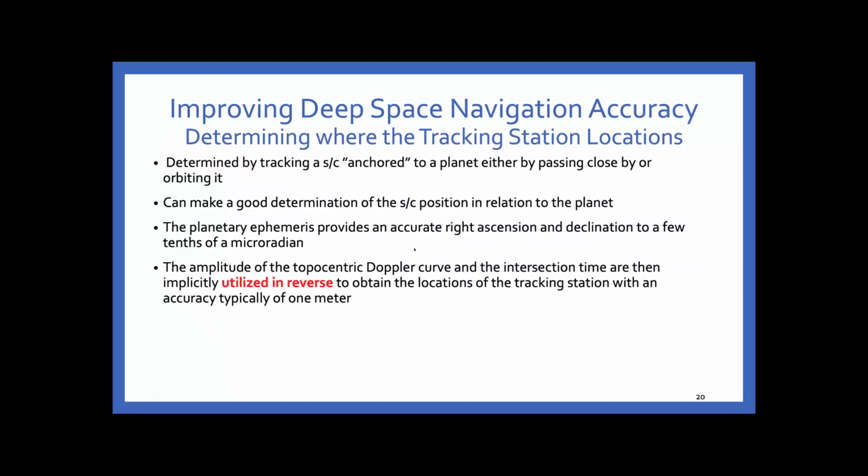Now, of course, traditionally, the location of any particular spot on the Earth is determined by geodesists, and they introduced this concept of a datum, which is a mathematical model of an ellipsoid or something that we think best represents the surface, let's say, of North America.